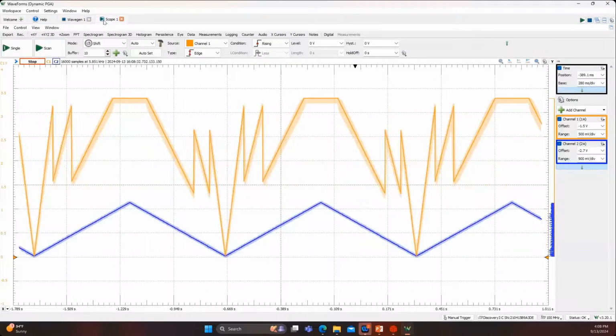Great, now let's pause and we can start to explain the results here. As we are increasing the input voltage, the op-amp output is also going to increase until we hit the window comparator maximum, and then you will decrease the gain in order to drop back within the range you allow. And then this process will happen again, and it will continue to increase until it hits that window comparator maximum, and you decrease the gain to decrease the op-amp output.